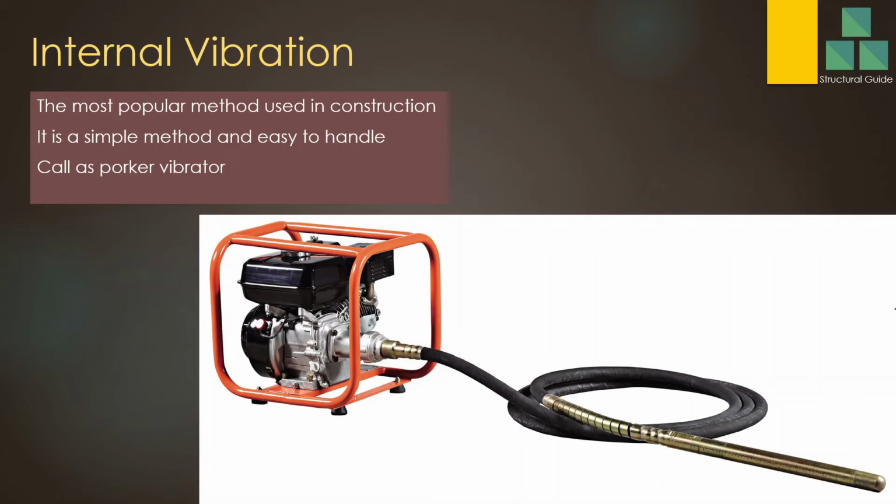Internal vibration. This is the most frequently and most widely used and most known method in the construction industry. This is very easy. There are machines that work on fuel, or there are electric machines also. This is one of the oldest methods, and it is very easy to handle and very simple. This method is also called the poker vibrator.